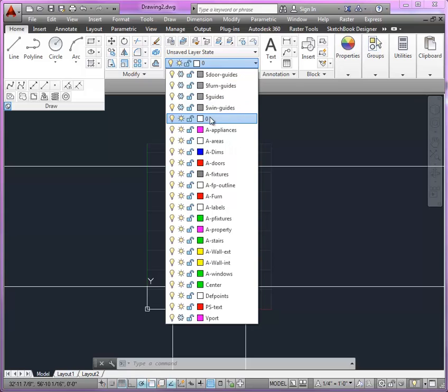You can see that the way I got these layers to show above this layer is by using a symbol. Okay, that way I can separate layers that I use just for guides as opposed to layers that I use for model information. Also, later on you'll learn about CAD standards, and you'll notice that all of these are annotated with an A for architecture. Right? So you have the major discipline, and then you have the category of information. So let's thaw some of these layers here that we can use, and I'm going to thaw the guides layer here.